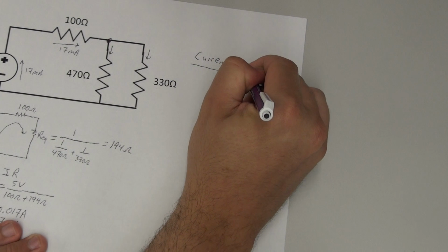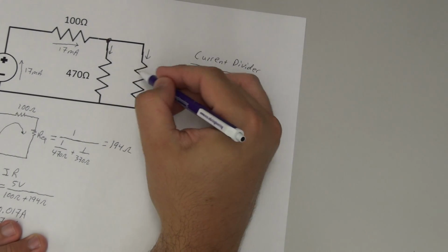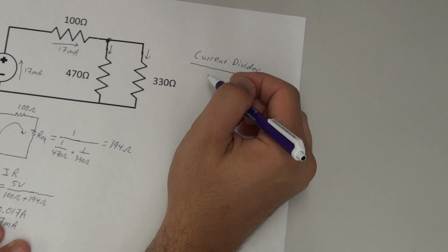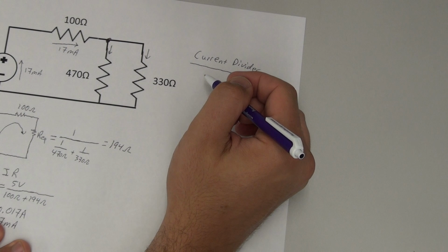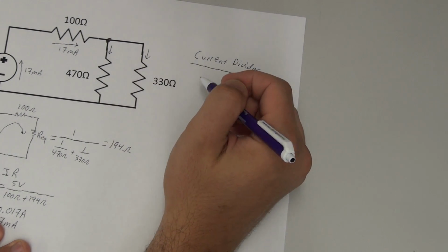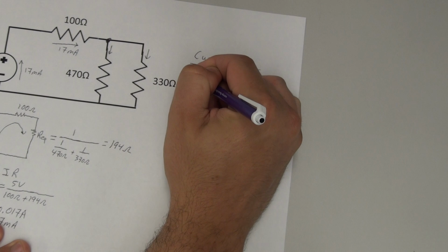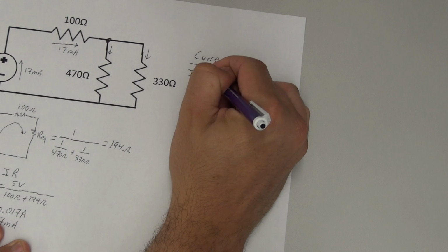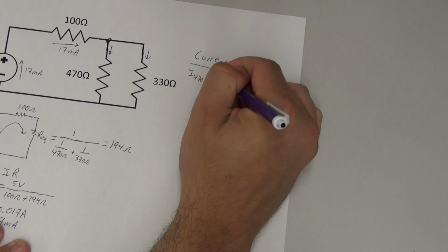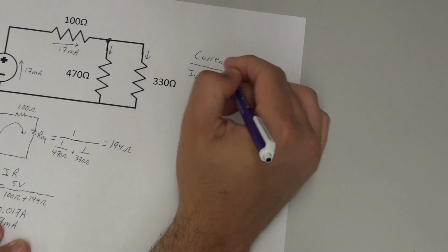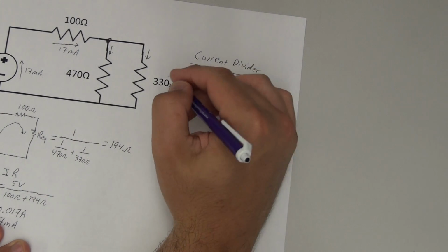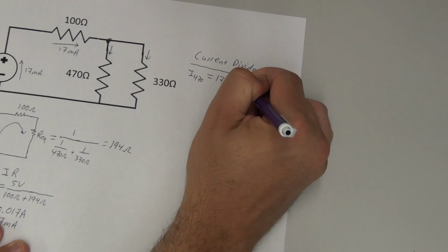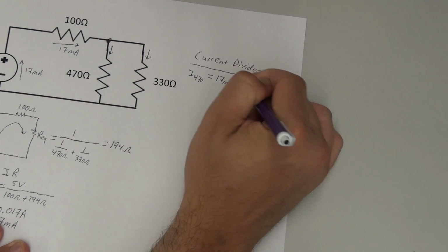And a current divider divides the current amongst those two branches proportionally. And so if we have 17 milliamps coming in, then what we're going to do is have an inverse proportion to the different resistors. So I470, that is the current through the 470 ohm resistor, is actually going to equal 17 milliamps, that's the total current coming in, times the opposite resistance, the resistance of the opposite branch, which is going to be 330 ohms,